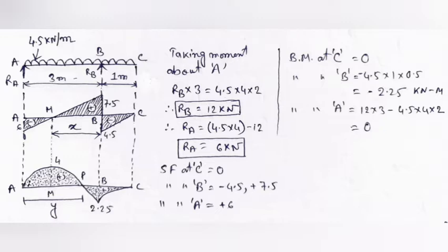First of all, shear force at point C will be 0, and from C towards B it's negative for UDL, going downwards in a straight line. Previously we have done the shear force diagram for UDL. Here also the same diagram rules apply, and the shape of the diagram will be the same as previously. So for the downward load it's going to be a straight line downward from C point to B point.